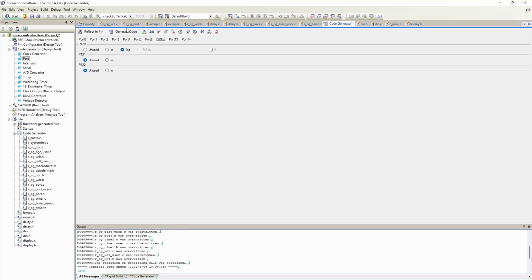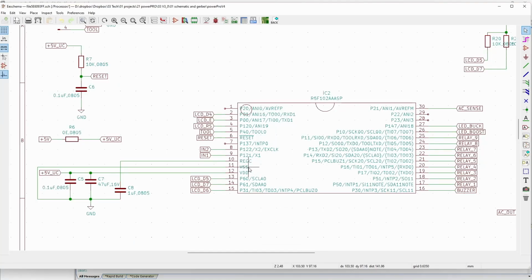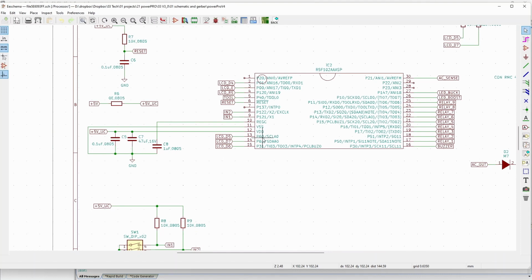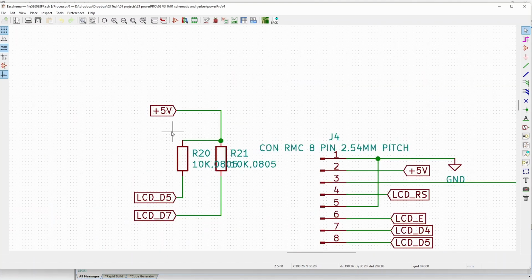And there is one more thing here. Even in Microchip, one thing you have to remember is to make sure that you have selected the pin type correctly. For example, in here, for port 6 the output will not go high. It's like an open drain connection. Basically what it means is even if you make that pin high, it will float. It will not give you 3.3 or 5 volts which is required. Low will make it ground. So if you are using it to drive something as an output, you have to put a pull-up resistor.